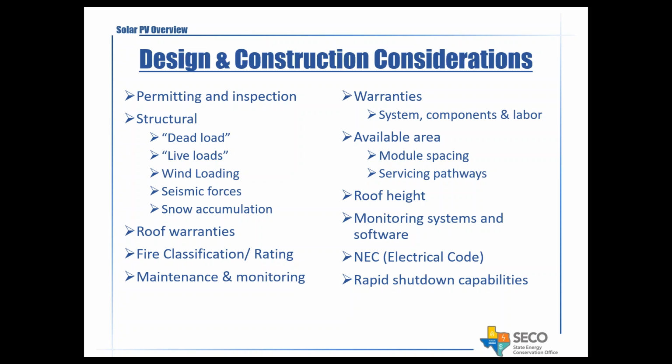At one of the existing locations, everyone thought it was a great opportunity to put a PV system there. However, when they went into the electrical room, they realized they already had 6 disconnects, and they couldn't install another disconnect because it would be a violation of the National Electric Code. For that, they needed to upsize and consolidate all their main switchgear. When you put all of those costs into account, it became not very feasible to do this. So just something to keep in mind.